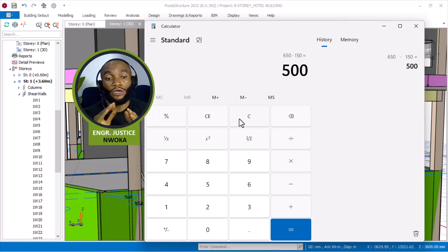Okay, or let me say proceed into the beam. It stops beneath the beam surface. Okay, that's fine. So with this right now, we have known that the beam is 500 depth. Now then the height of our story is 3875. Subtracting 500 from 3875, what do we have? We have 3375 millimeter. So this is the actual height that the block wall will occupy.